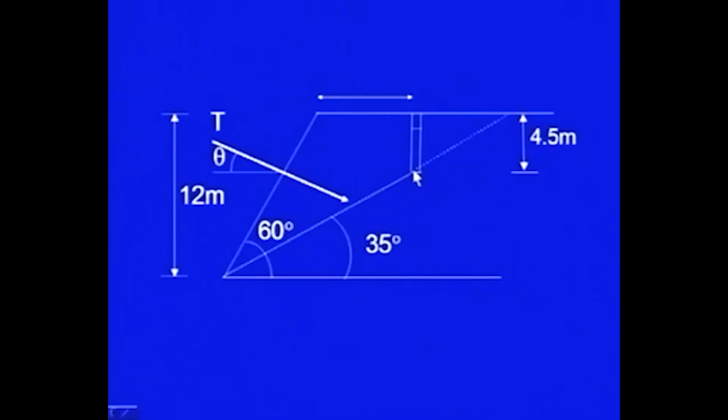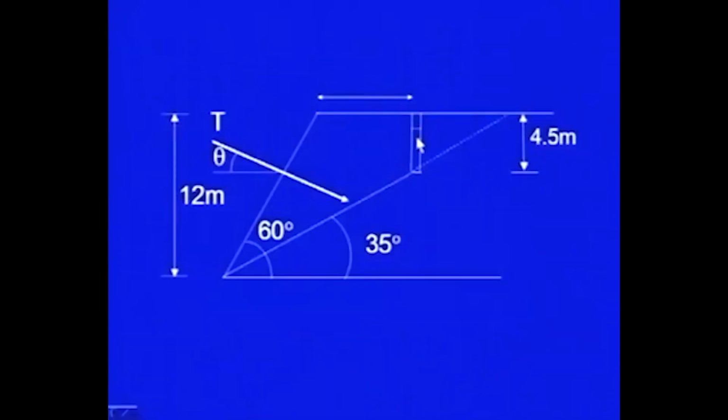So one can do the parametric analysis and then you can find out what are the variations of the factor of safety, how the slope is going to behave in different drainage conditions. Drainage conditions means, for example, if this is completely choked or it is completely free, or here the tension crack is filled with water or it is not filled with water, it is completely dry. So the extreme values you can find out and then you can have some plan. For example, during rainfall season some warning systems etc. may be designed.